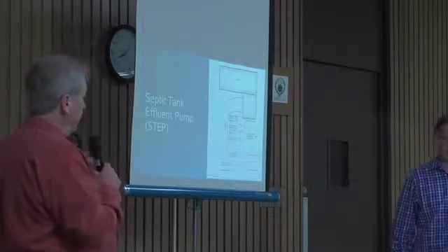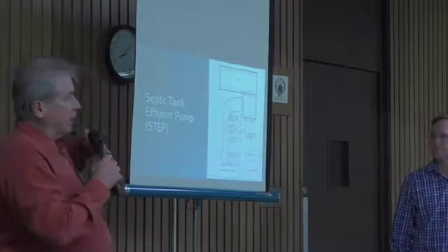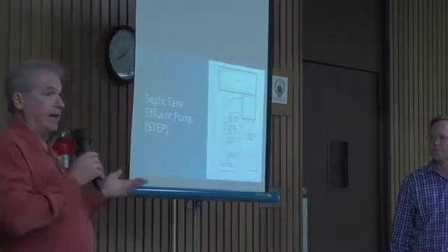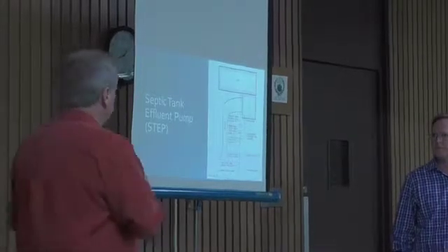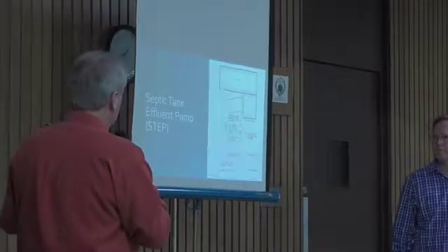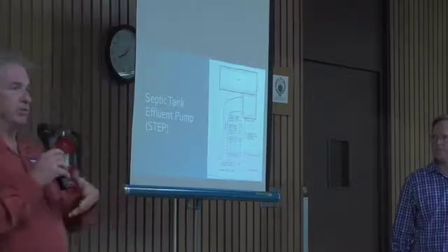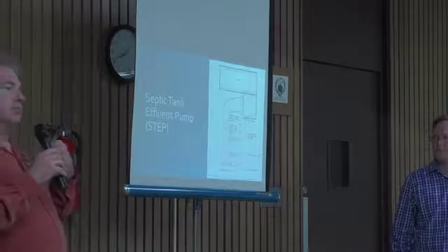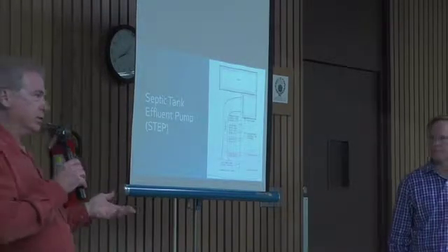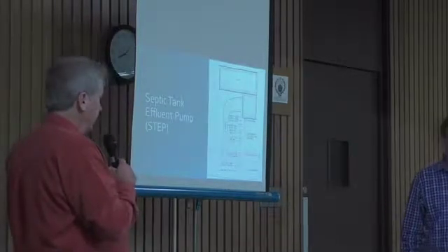One way that's been done in the past is what's called septic tank effluent pumps. And that's where if you have septic tanks that are suitable, that are not leaking and a good, correct size, you can put pumps in the septic tank, or you can add a pump system after the septic tank, and you're pumping that septic effluent to the treatment facilities or to a centralized disposal area.